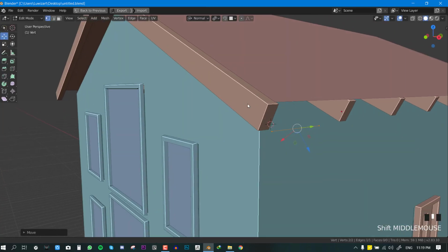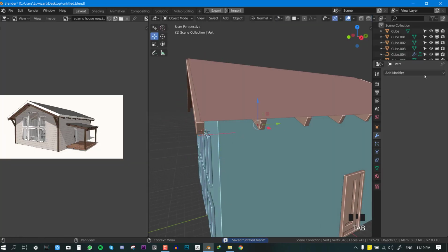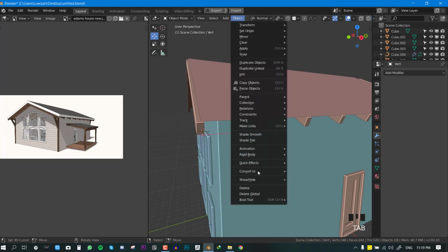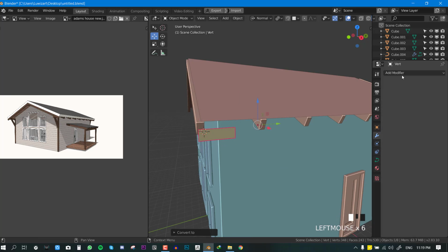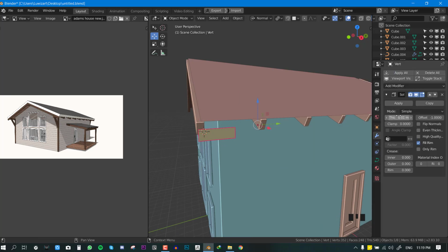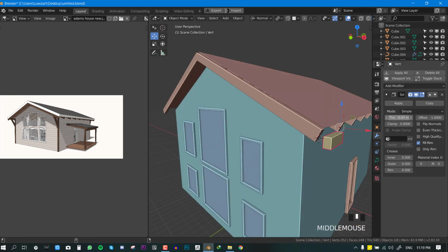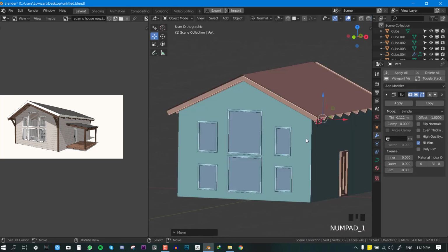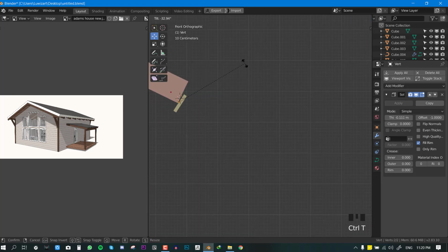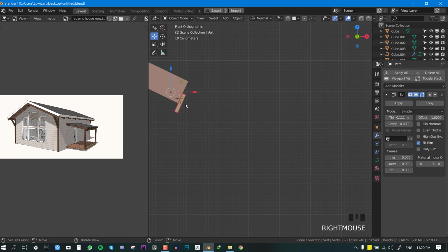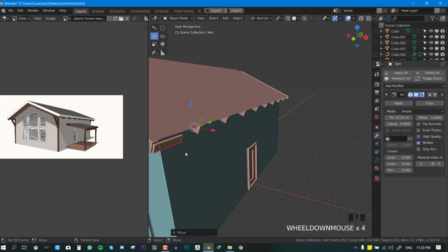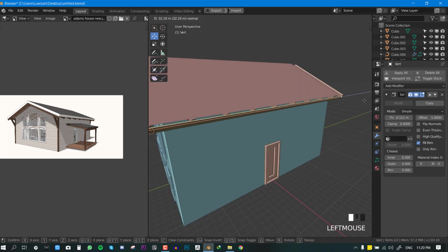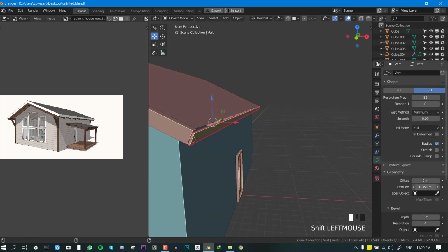So after that, for the side structure for the roof, same drill that we did for the main structure, we'll add an edge, make it a curved mesh, then extrude it slightly, and then we can add a solidify modifier, and then we can just quickly tweak it to match what we have going here. So if you hold Ctrl T in the curve edit mode, you can tilt a curve, and that's what I did here. And with this, I can just drag it and everything's going to fit perfectly.